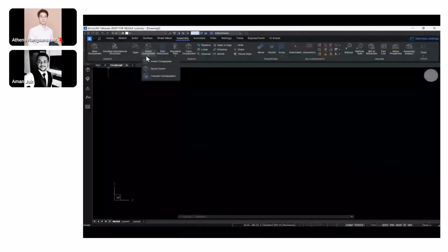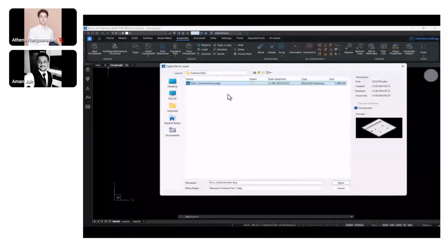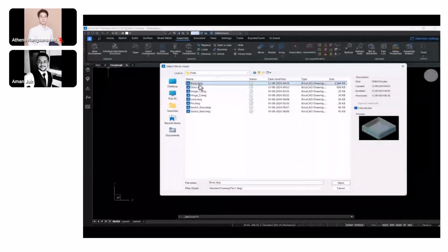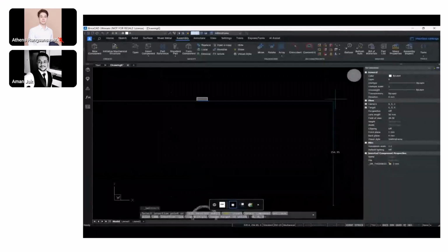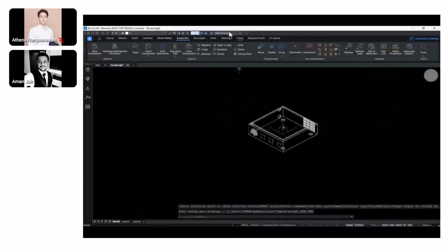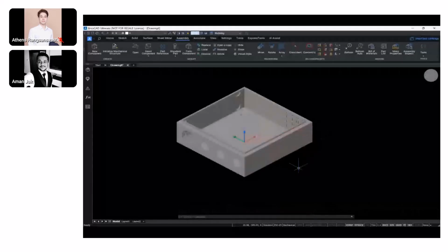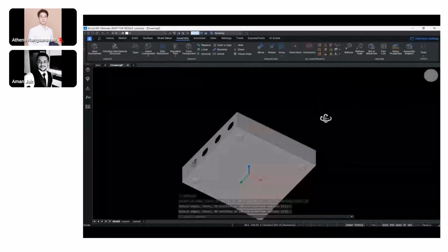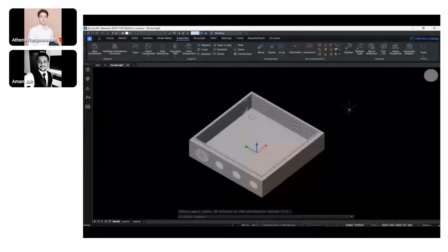We'll insert the component, the body first, because that forms the base for our main assembly. The door would be placed on top of this. So let's place our body, and let's fix it so that this does not move, and this acts as a rigid constraint. So we'll make it rigid so that the body does not move as we are applying the constraints on top of the other parts after inserting the components. Right? So let us constrain this fixed and insert.